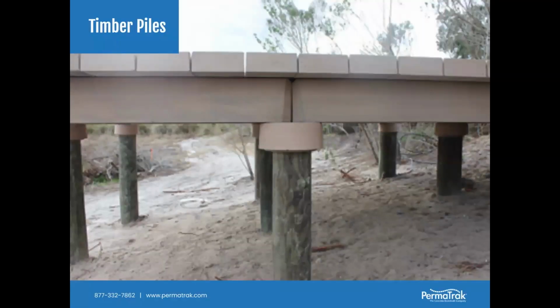I'll start with the timber pile system because that's the most common, certainly the most common that we see here close to where I live in Charlotte, North Carolina. A timber pile system is a good, inexpensive foundation system, typically driven, could be vibrated into place. Fairly light pile system, could be installed with an excavator. Doesn't always require a hammer and a drill rig. So it could be done with lighter equipment if needed.